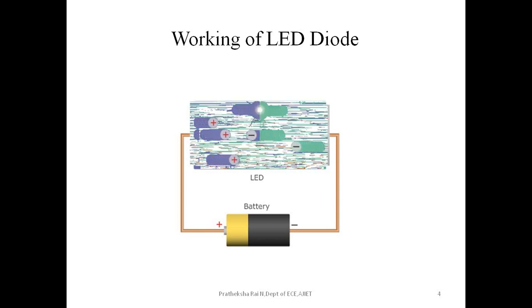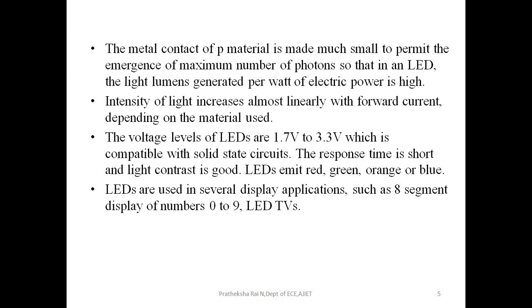Okay, so how does a light emitting diode get its color? That's the question. Unlike normal signal diodes that are made for power rectification or detection, that is PN junction diode is usually made from germanium or silicon semiconductor materials, right? But light emitting diodes are made from exotic semiconductor compounds such as gallium arsenide or gallium phosphide, gallium arsenide phosphide, silicon carbide or gallium indium nitride, all mixed together at different ratios to produce a distinct wavelength of color.